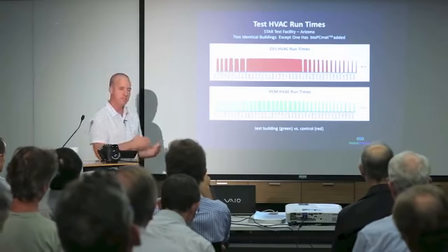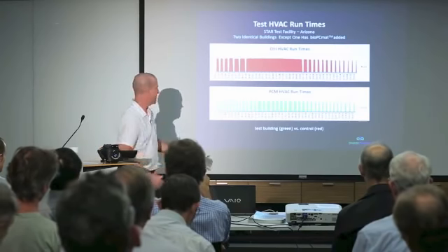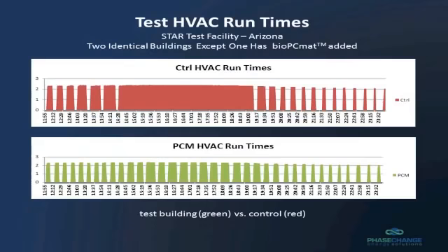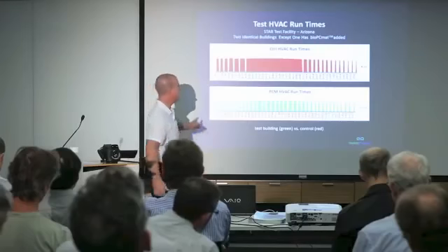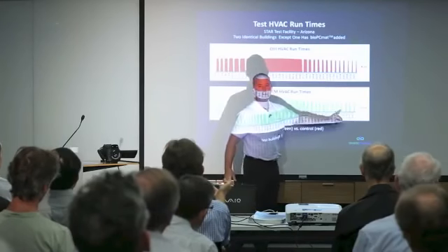No, not at all. The phase change happens throughout the day. So what's happening here is the aircon's coming on. It's realising it's not that hard to get it down to the temperature because the phase change is doing a lot of the work for it. That's the normal cycling of an aircon. So it comes on, it cools it, it realizes, I've got to 22, I'll turn off again, because the phase change is helping the return air be cooler. So it's gradually liquefying. Eventually it's liquid, but by then it's nighttime.